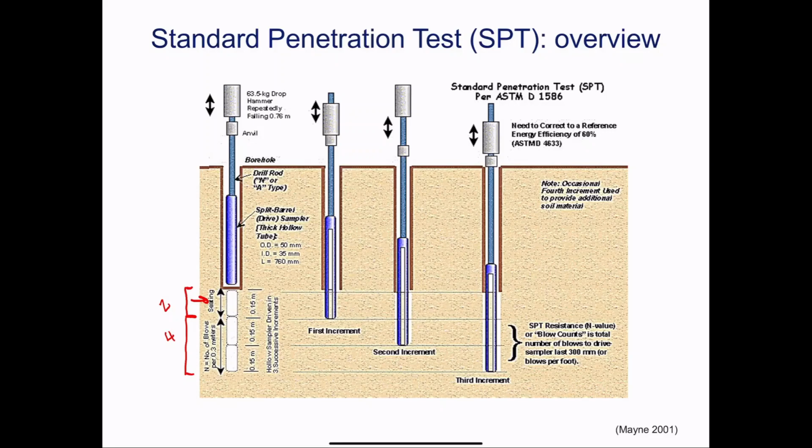And we mentioned that when we carry out SPT testing concurrently, we have the advantage of obtaining some sort of soil sample on the ground. And this soil sample, although highly disturbed, can be used for simple index testing and classification. You can also use it for PSD and also moisture content. So this is a quick overview of what we discussed in the last class.